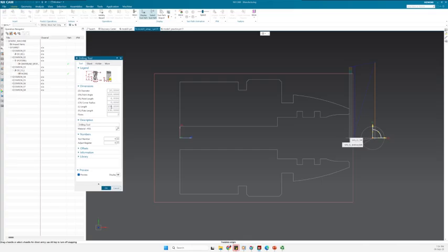For now, I will select this 20, this 118, it looks okay, but anyway, you can check it out. As you can see, 150 is the length of my drill, but the length of my part was about 155. So if I put 150, considering that there would be the shank after that, there would be a collision anyway. So let's say I have another drill, tailored for example, I put it longer here so that there wouldn't be any problem. And then there would be two flutes and that kind of thing.